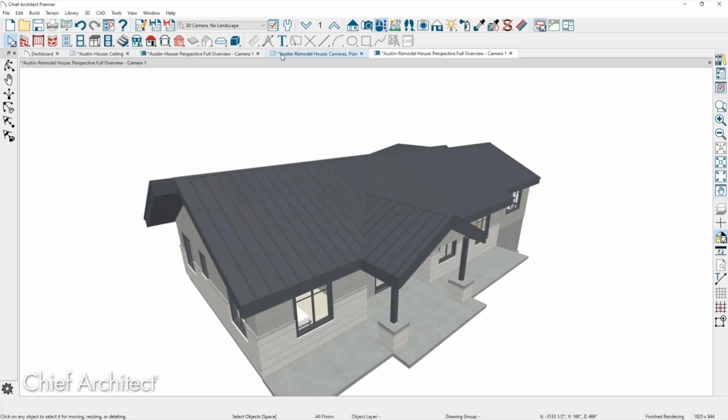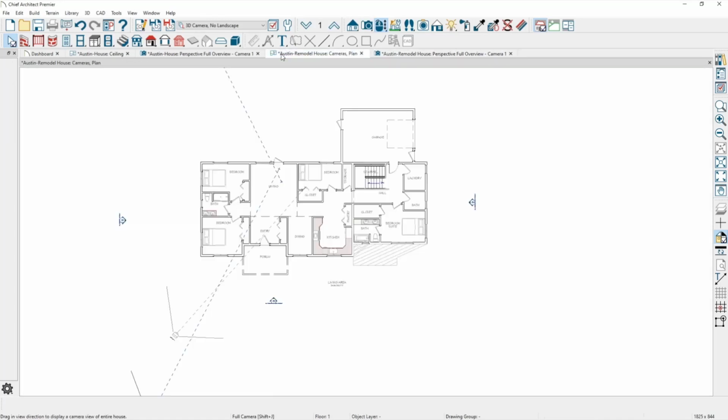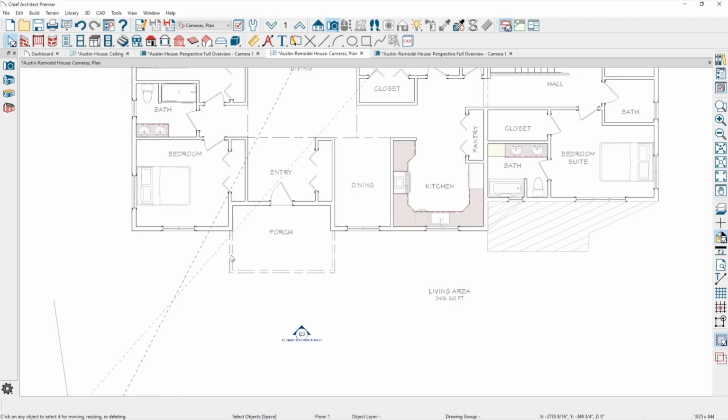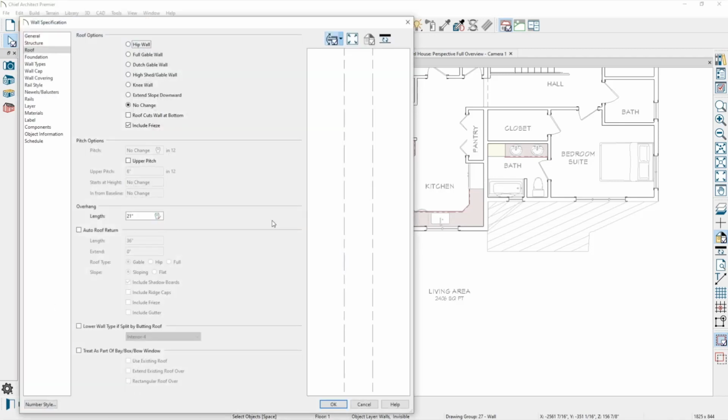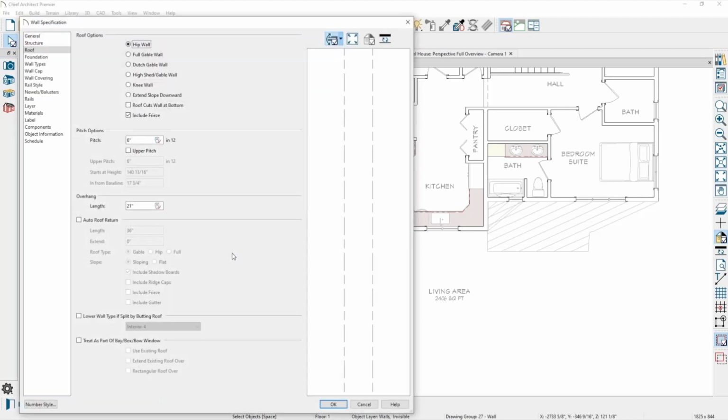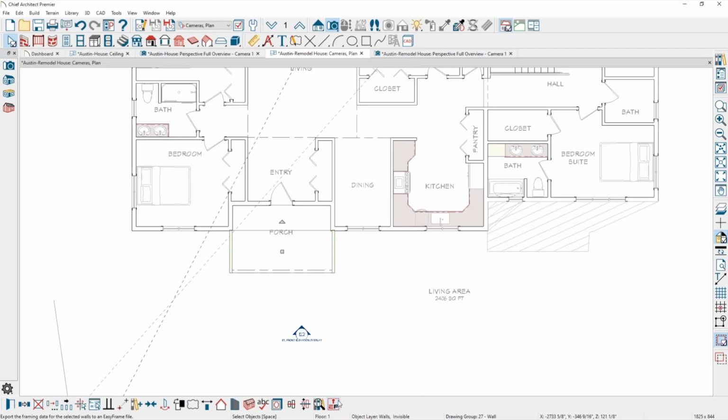And I'm finding that some of those roof planes coincide together. So if I try to change the pitch of the gable roof, it'll also change the pitch of the hipped part that coincides with it. But then that part of the roof is now not connected. It elevates above the rest and is not connected to the rest of the roof.